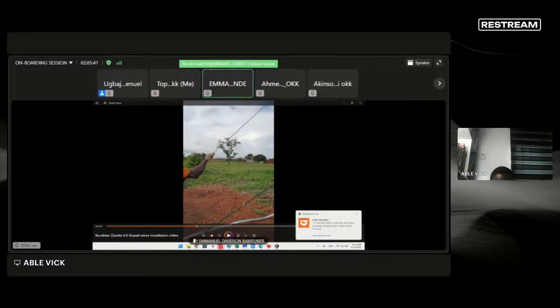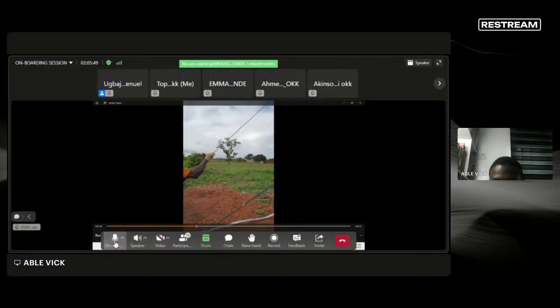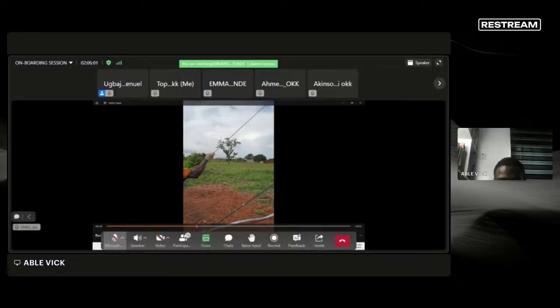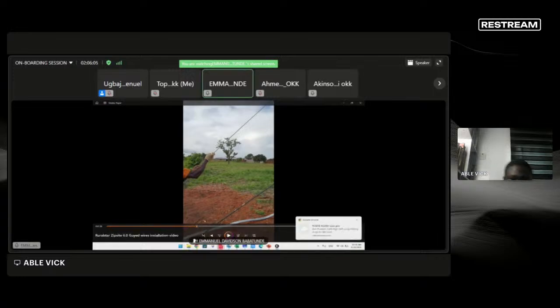You understand it? Pay attention to the material. If it's too rocky, stony materials cannot be compacted. There will be too many gaps in between. The compaction will be zero. Fine materials like fine sand cannot be compacted. No matter how you compact it, you won't achieve anything. If you go back tomorrow, you will see you can shovel to excavate all the sand away. That material cannot be used for compaction. So pay attention to your material.